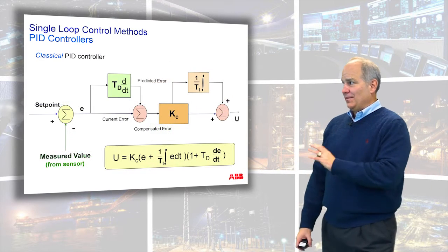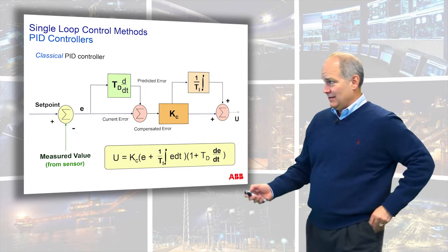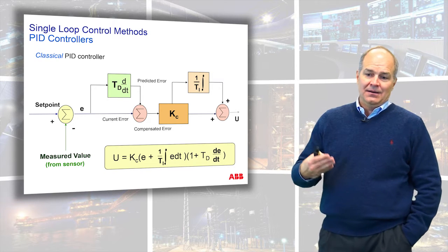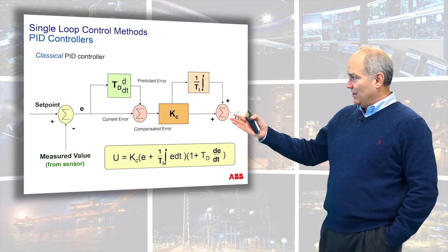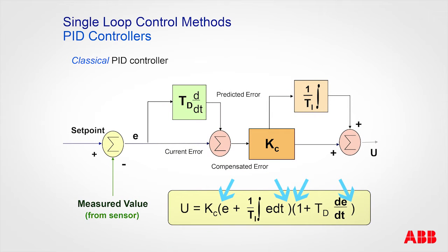The third form, this looks really freaky when you first look at it, it's like, well, shoot, this is what's called the classical mode of the PID algorithm. But if you look at it, notice it's got two parentheses. So what's happening, and I like to speak of it in terms of, if you look at this, set point minus value is the error. The error goes straight through here.